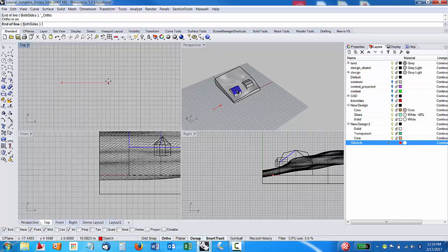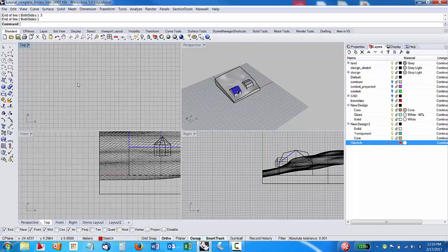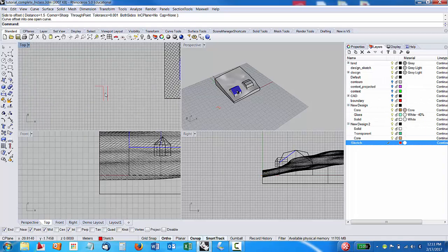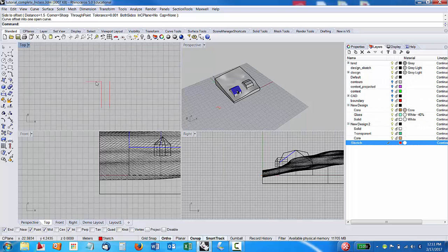So I'll make a 3-meter wide room. 3. And I'd do another bearing line down this way, say for 5 meters. Maybe I want to make that, so I'm going to offset that. I want that to be like a kind of circulation core, so maybe I'll say that's like 1.5 meters. And then I'll maybe just kind of,